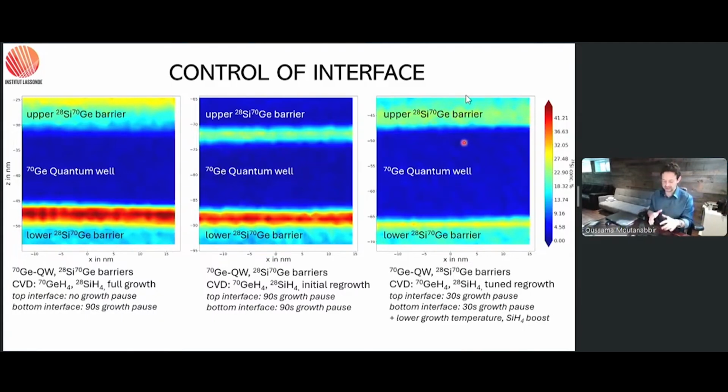Okay, so here I would like to conclude this part. This is the entire community working on silicon germanium: when you switch to isotopes, you have to engineer your reactor not to consume too much of these precursors. And second, you have to engineer even the substrates in order to avoid wasting this element. A small bottle, if you put it in an industrial reactor, you might just open it and it flies. Everything will go away, and you cannot grow enough samples.